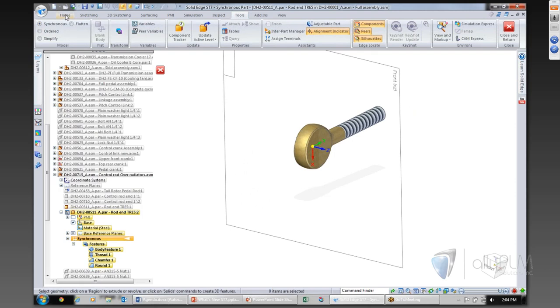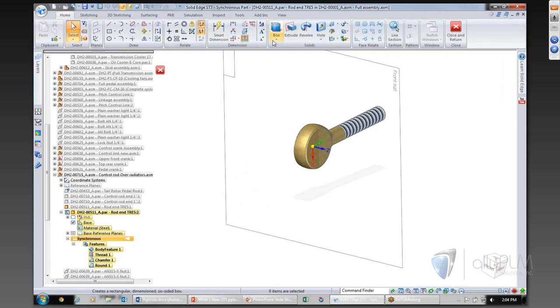So in ST7, this type of part can be created in just a couple of clicks using the new spherical primitive shape. So the spherical primitive can be used to create a spherical part or to generate a spherical cut, as we were going to use in this case. So I'm going to do a cutout of 8 millimeters.